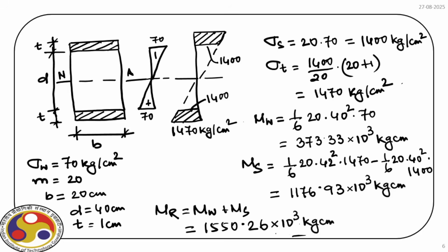So now you see, if we have a beam made of two different materials, then again we can apply the same bending stress distribution model, and we can find out the total moment of resistance for that particular cross section, which is contributed by the individual materials.